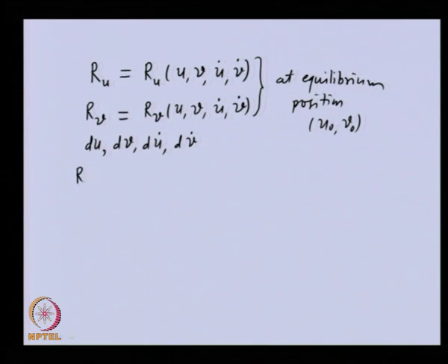So the fluid film force now will be written as, so this fluid film force we expect that it will be changing because of this disturbance. Like this. Similarly, this particular one is in the u direction, and a similar variation will be there in the v direction also. This particular function we can expand using Taylor series expansion.